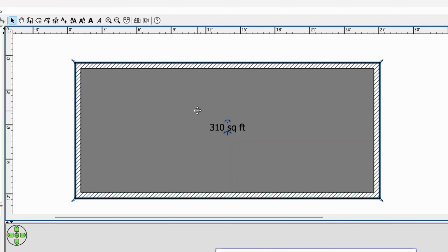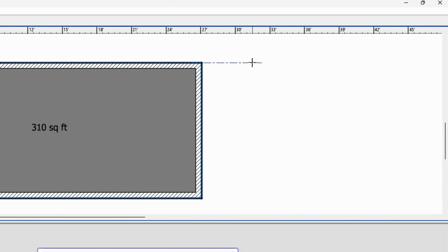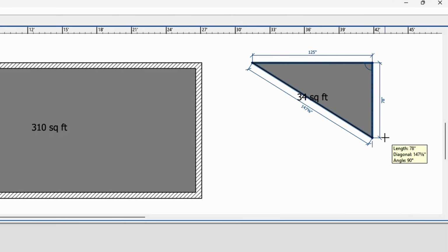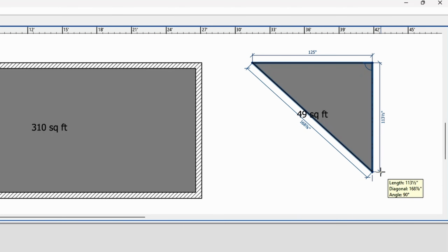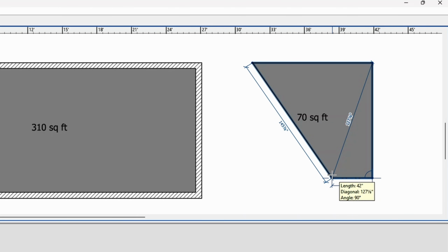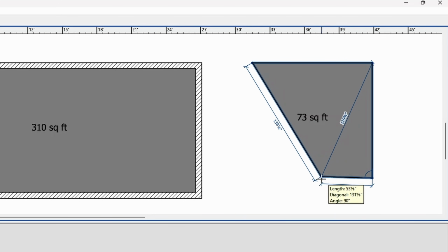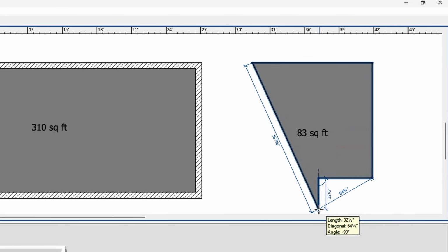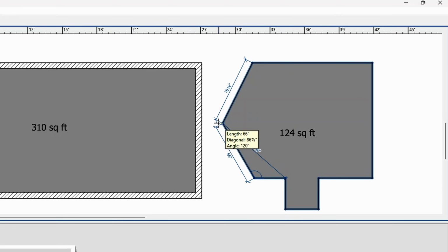To create a floor manually, just go back to the toolbar, click Create Rooms, then click on your plan with your left mouse button. Just keep clicking to place new points. Each click adds a new corner to your floor. If you want to disable auto snapping, just press and hold the Alt key. Or turn off the magnetism tool in the toolbar. To stop drawing, press the Escape key.